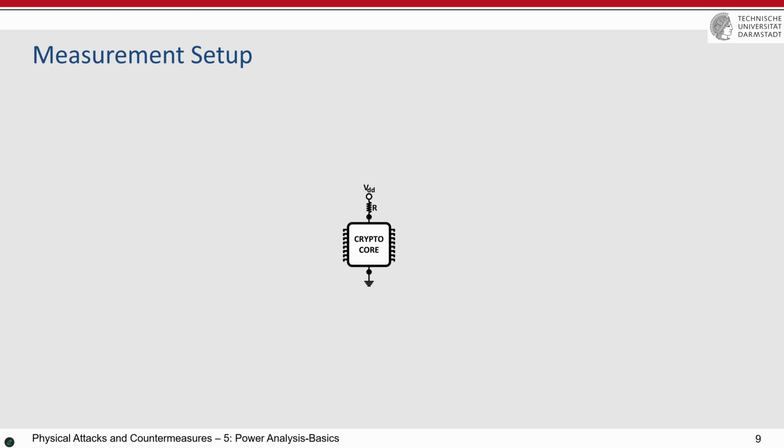This is also the things that I explained, but in more detail. We put the resistor at the top. Usually this is our choice. I will explain to you why. This is actually our favorite case, that you put the resistor at the VDD line instead of the ground line. Why? Because in some devices, particularly in new technologies, there is a VDD, which is, for example, 1.2 volt, for the technologies that I explained, 65 nanometer.